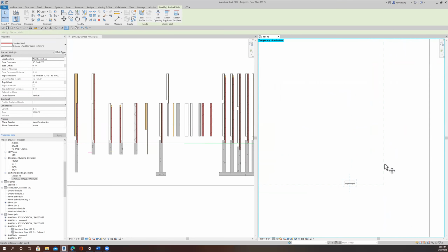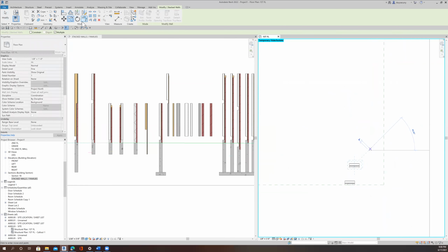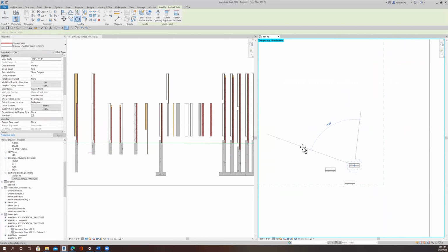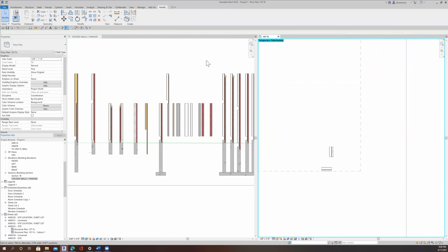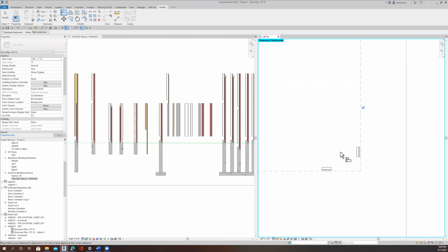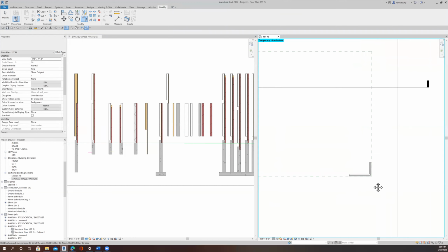I can copy that again over like that. And I want to rotate it 90 degrees. Let's see if I can do that real quick. Oh, I copied it again by mistake. So I'm going to highlight that. Rotate it 90 degrees. And I don't need this one, so I'll delete it. And then I will align this line. And then using the trim extend, which I still call fillet from the AutoCAD days. There's the corner of my garage.